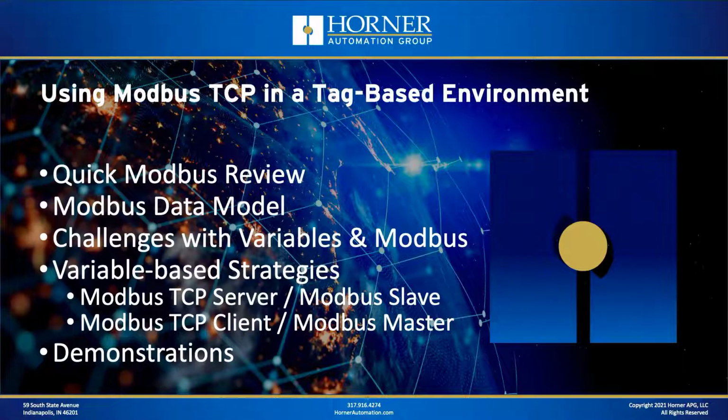We're going to spend just a minute or two on a single slide doing a quick review of Modbus, because we've covered it a lot here on the Horner channel. We're going to talk about the Modbus data model because it's relevant for today's discussion. We're going to talk about the specific challenges when you're using a variable-based or tag-based environment with a protocol that's more of a register or memory-based protocol like Modbus. And then we're going to go through some specific strategies for implementing Modbus, whether you're talking about Modbus TCP as a server or slave, or Modbus TCP client or master.